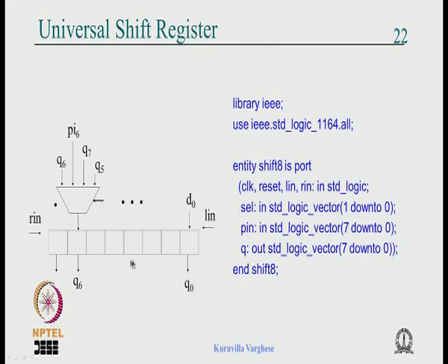So that is what the real hardware is, and now we write the code. When we write the code you could write it as one 4 to 1 single bit mux repeated 8 times, or as I said you can think of a huge mux where the 8 bit output is there, and the input is also 8 bit, because after all we are connecting all the inputs down here. But you can expand it to bring clarity to it. Whichever way you view it, that is the hardware.